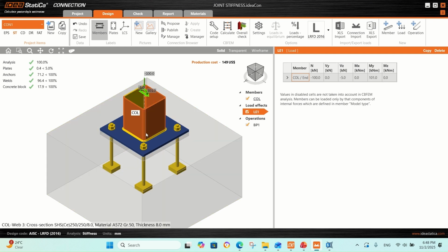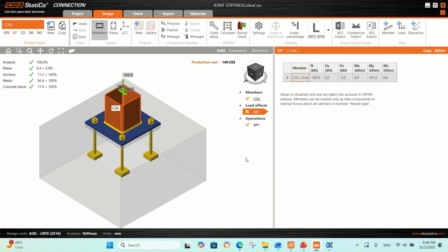However, one of the common mistakes is forgetting or ignoring the stiffness check, especially for cantilever columns or any structures sensitive to drift. For example, the cladding support, especially if we have brittle material like curtain wall, it's mandatory to check the stiffness of the fixed connections.